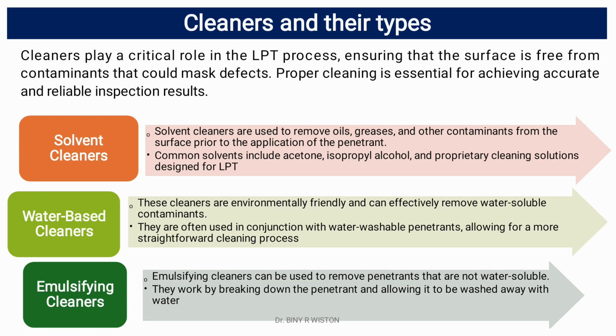Cleaners. Cleaners play a vital role in the LPT process, ensuring that the surface is free from contaminants that could mask defects. Proper cleaning is essential for achieving accurate and reliable inspection results. Types of cleaners are solvent cleaners, water-based cleaners, and emulsifying cleaners.